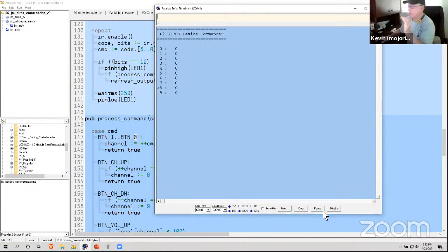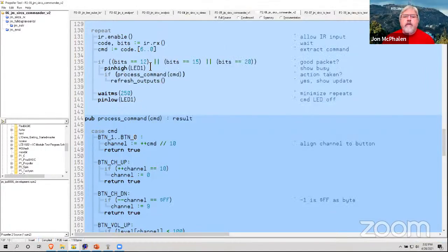So let's say you've sent 3 packets, your code here will respond to the first valid packet. Let's say that your first packet is corrupted and it doesn't compare to any of the button presses. So it negates that. Then the second packet is a number that jives with the command, and it takes that as a valid command. Yes, and then you'll notice in all of my handlers, when I get a valid command, I throw in a 1/4 second wait, because that would get me past all of the other packets in the frame.